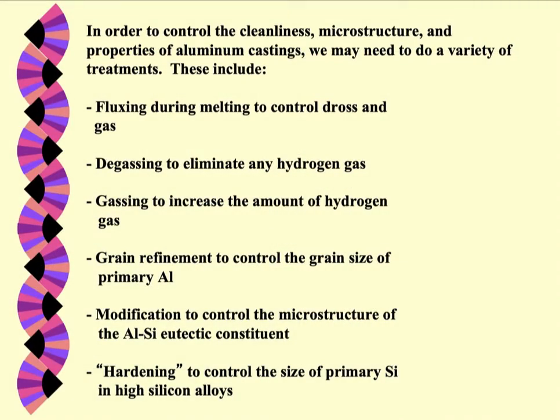And I can show you some microstructures later on in this lecture. But these little crystals form during solidification. The coarser those are, the lower the mechanical properties. The finer they are, the better the mechanical properties. So you might want to put some special chemicals in there that make it have a finer grain just by adding those chemicals in there, or nuclei, we call them.